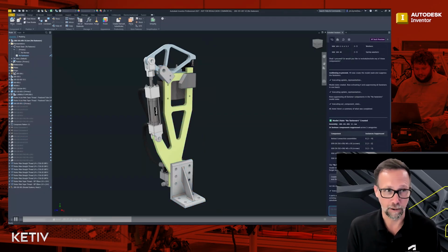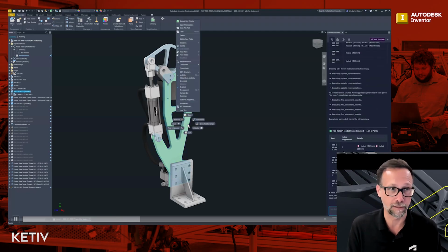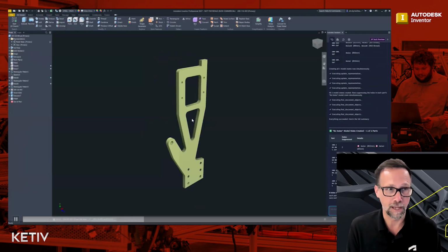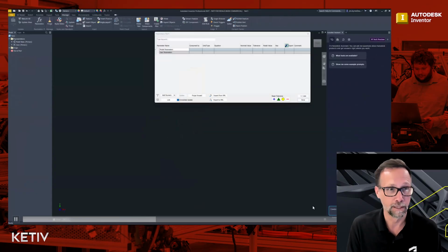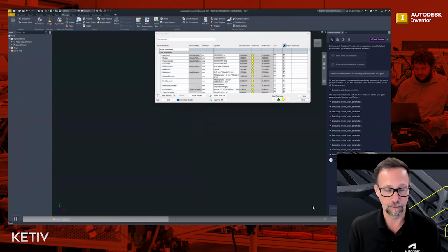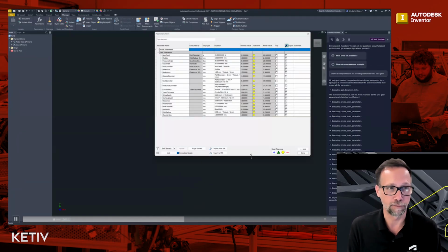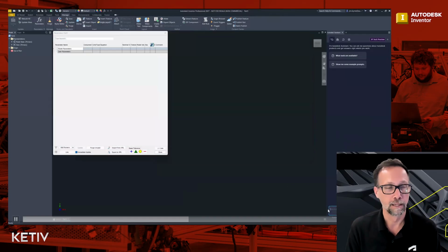And the really neat thing here is you don't need to open any of those models. If we select, for example, 50 parts in the design, it's going to create those model states for you without even seeing the part open. And here's the parameter generation. This is a spur gear. It will create all of the standard parameters for that type of object. And it does it in less than a minute. So this is pretty amazing if you have a standard part that you're working on.